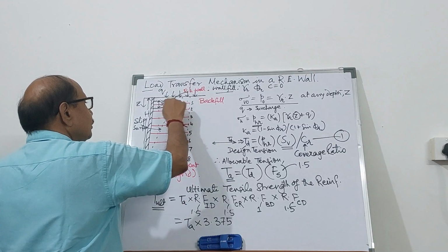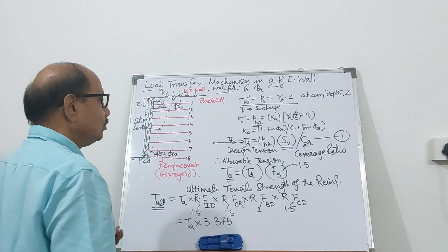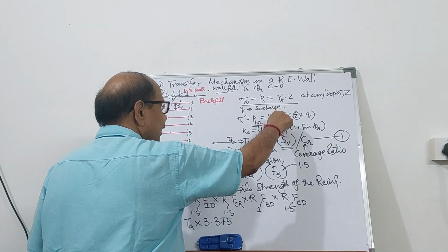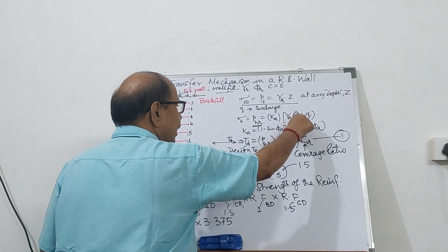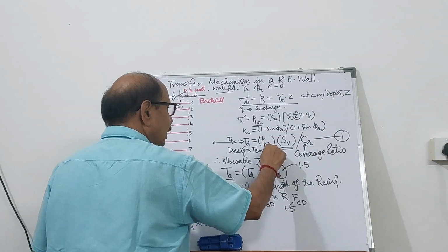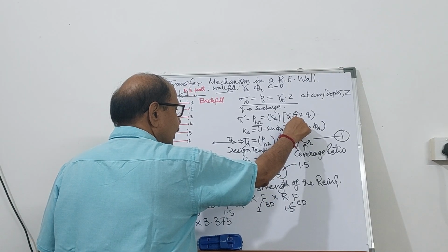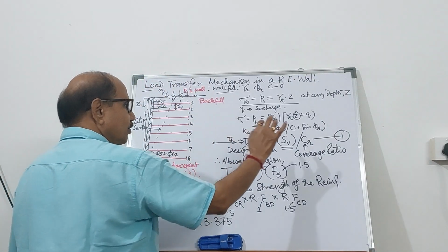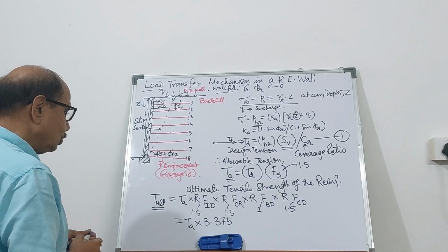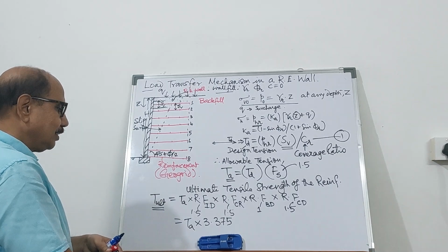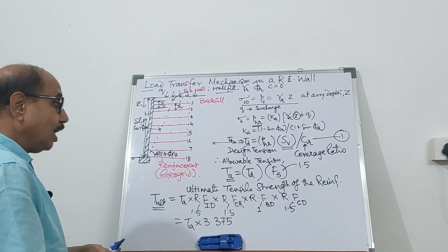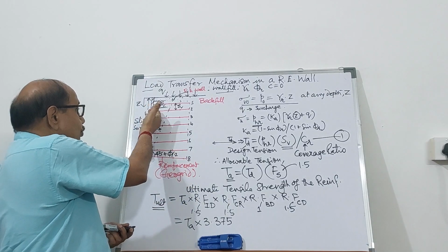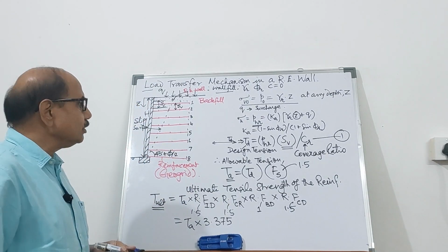So in the wall fill zone, you can calculate PHR as Ka into gamma R into Z plus Q. And once you calculate this, which is a function of Z, multiplied by the vertical spacing divided by the coverage ratio, you are in a position to calculate the ultimate tensile strength of the reinforcing element that you are going to use in RE walls.